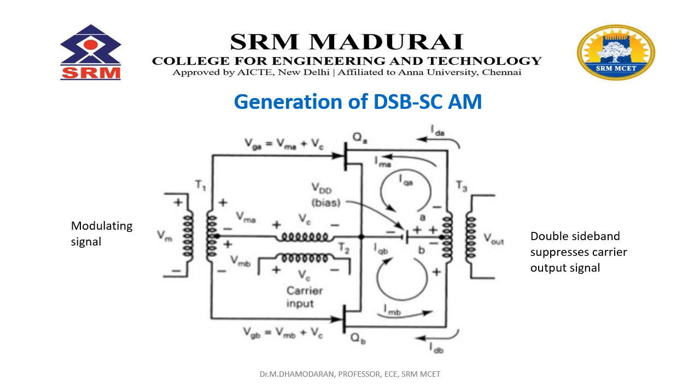This is a simple basic diagram of the generation of a double sideband suppressed carrier AM signal. The input is a modulating signal, that is, the information signal. It goes through a transistor circuit that acts as a gate circuit. We have FETs in this, and QA and QB act as a switching network to get the continuous output. We can get both the upper side and lower side AM signals from this. Finally, we get the double sideband suppressed carrier output signal.